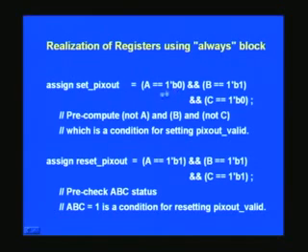It's not the only alternate way, because when we are going through hundreds or even thousands of statements, we may not be in a position to go all the way back and find out what the bit precision of a particular signal is. So it's always good practice to indicate that. So this is what it does here. Another important thing is, when you write a statement, it's good practice to have good comments. What is obvious in the statement, don't state that, because it's already stating what you want. So put it in plain English-like language here.